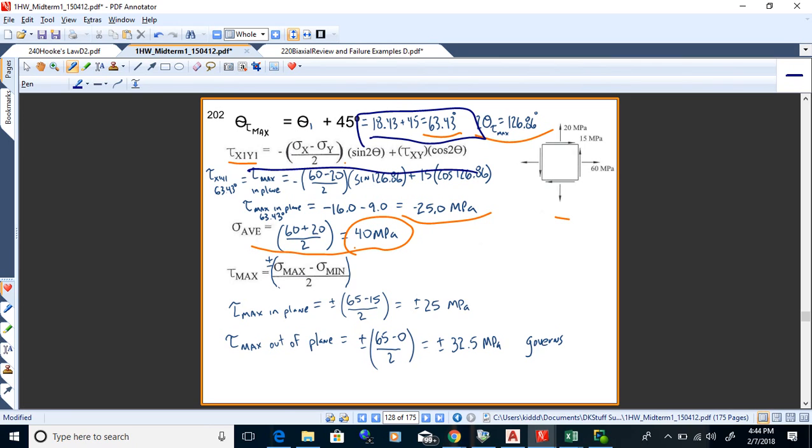That way you'll get the sign of the shear at a given angle. It's very simple to draw it up if you need to do that. So if you want to make sketches, beware of formulas 28 and 29 because they make it a little bit more challenging. That's all I want to say about that. If you're good at it, you can use them. But the simplest way is just get the angle, plug it into the general formula. And that holds for both normal stress and shear.